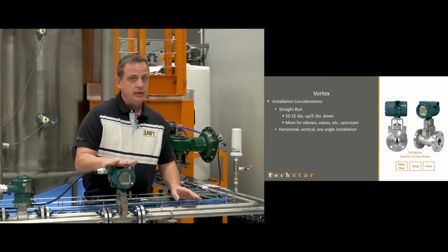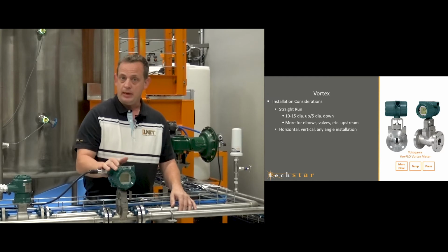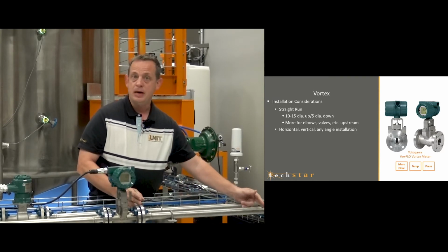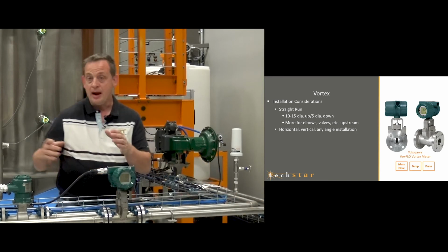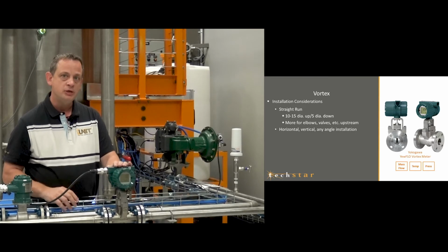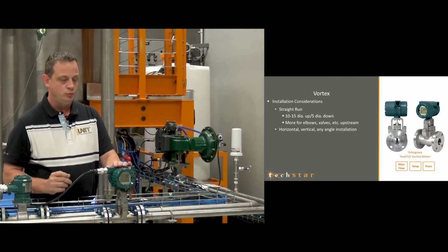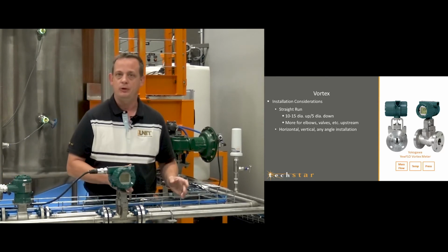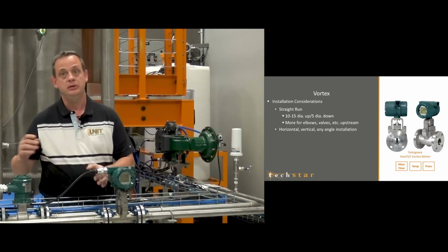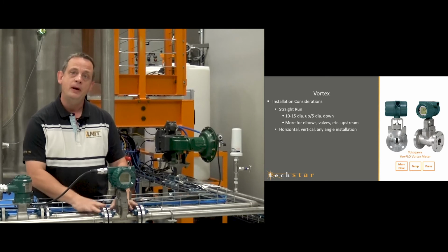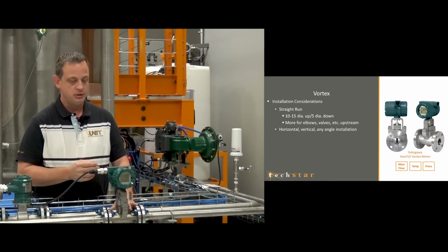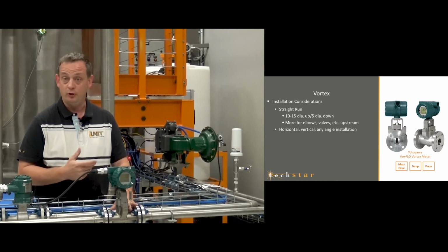Vortex meter will work in gas applications or liquid applications. So in a liquid application, usually about maybe 10 pipe diameters upstream, 5 pipe diameters downstream would be preferable. For a gas application, we want to extend that a little bit. So you could have 15 to 20 up and maybe 10 to 15 down. Okay, really the more pipe diameters you have to really ensure that good flow profile is going to be preferred.